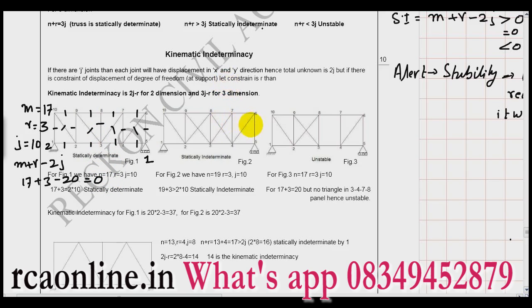Now see the same truss with two cross bracings in the second and third panels. If you calculate, M comes out to be 19, R is the same 3 and J is the same 10. So what do I get? It is 19 plus 3 minus 2 into 10. So static indeterminacy is 2.